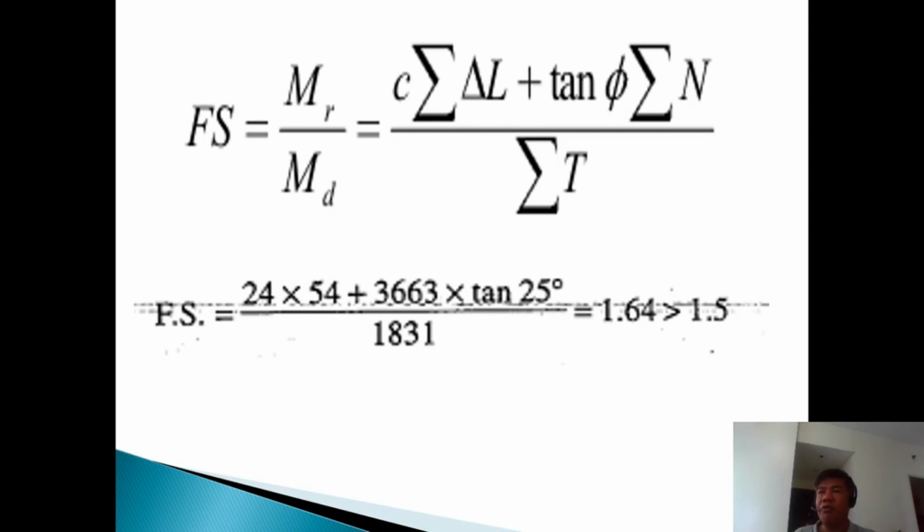It is only for 3 to 4 months during the excavation of the dry dock foundation in the sea area. Of course, you are going to block the seawater that will go inside the excavation area. So what we are going to do is construct a coffer dam all throughout, surrounding the area, which is a semicircle plot if you're going to look at it in the top view. Because it is just temporary, after 4 months we are going to demolish the coffer dam,